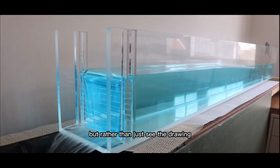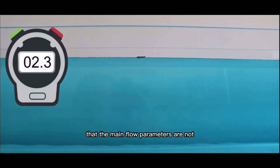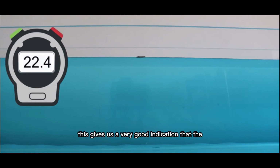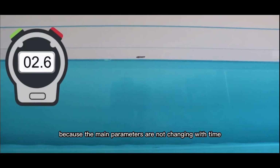But rather than just seeing the drawing, we can see this more clearly by looking at an example in the fluid. We can see in this example that the main flow parameters are not changing with time, as the stopwatch continues. We can clearly see that the depth, and therefore the cross-sectional area, are remaining constant if the depth is stable with time for an open channel flow. This gives us a very good indication that the system is in equilibrium, and therefore the discharge and velocity are also not changing with time. This is a steady flow because the main parameters are not changing with time.